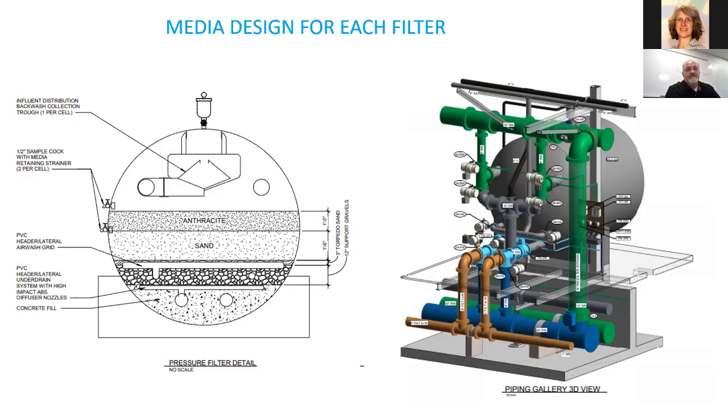So then at the plant, you're monitoring all of those parameters also, but you're doing those on a more regular basis, correct? Every day. Okay. And that's done for process control, to look for breakthrough in the filters, and that's also on the days that we pull water quality parameters.